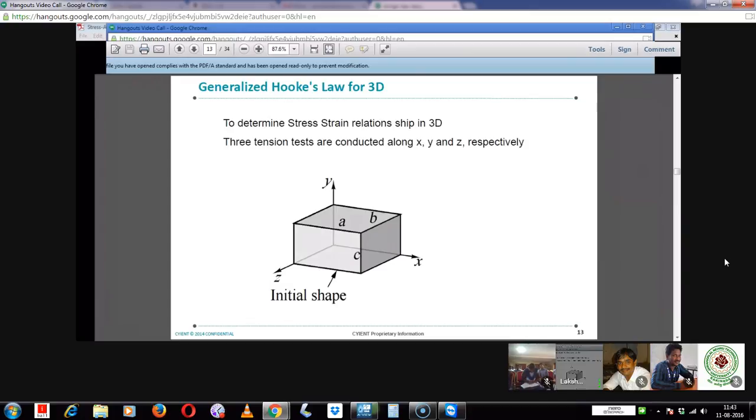So when the problem arrives, it is very important for us to understand which location is critical for us. Are the blades critical, or is the blade attachment critical, or is the turbine rotor critical? So we need to understand. Suppose the turbine rotor is critical, then we can go for a simple 2D axisymmetric analysis, and the blades are represented by some mass elements.